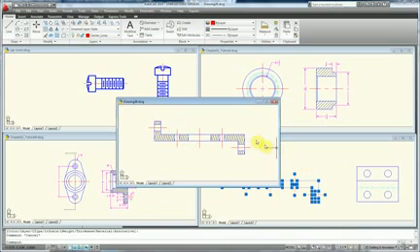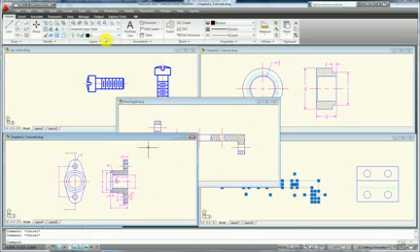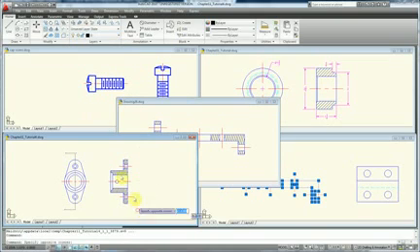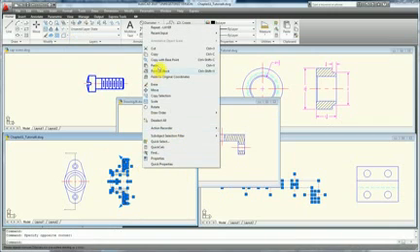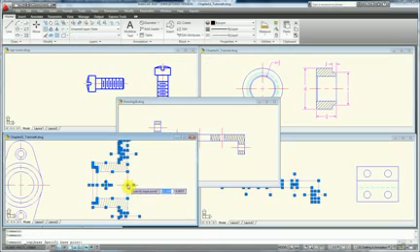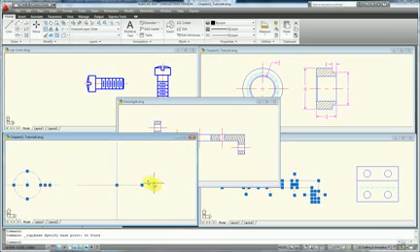Now that we've done this, we're going to add in the bearing. So I'll switch to my bearing drawing, turn off the dimensions. This time I'm going to right click, choose a window, right click and then copy with base point. Copy it about that base point right there. It's the same idea as I used for the block. I want it about the center line and about some reference base geometry like the bottom of the bearing because it'll be attached to the top of the base plate.